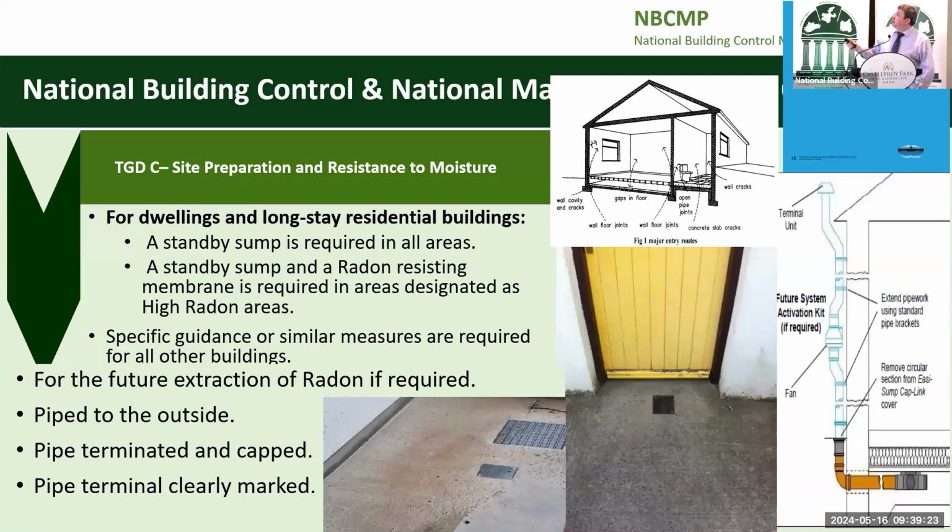This was the radon in existing buildings document. It's nearly 20, 30 years old, but it identifies the paths that radon could get into houses, at junctions here and walls. And even when you're designing the location of your outlet pipes, it's not practical to have it in front of the door, not practical to have it in the middle of the footpath.